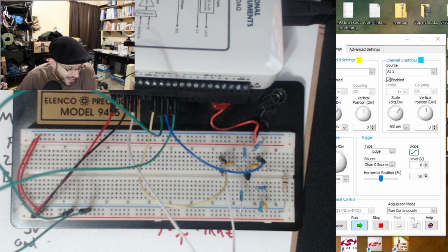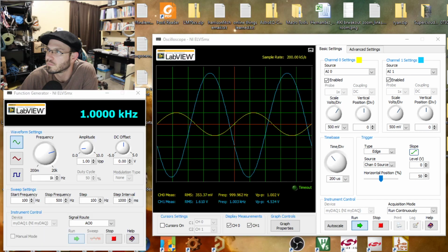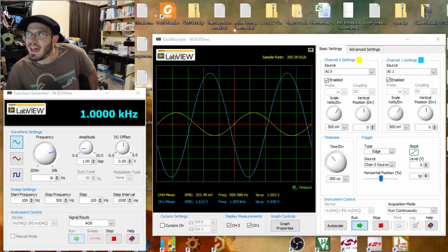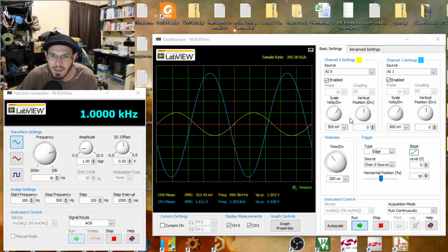Okay, so right now, let's go back to our oscilloscope. Check that out. Okay, so my channel 1 is set at 500 millivolts per division, and my channel 2 is set at 500 millivolts per division. Okay, I guess they're calling it channel 0 and channel 1. Why, when every other scope in the world uses channel 1 and channel 2? I don't know, but nevertheless, I will probably keep on making that mistake and calling it channel 1 and channel 2, as opposed to channel 0 and channel 1, because I've been using channel 1 and 2 for my entire life. Okay, I shouldn't say entire life, since I was a student.